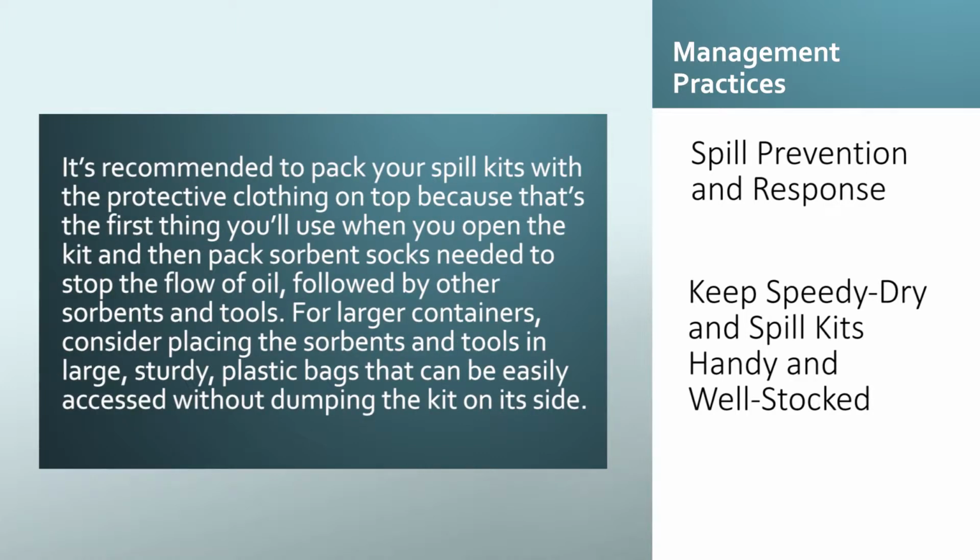It's recommended to pack your spill kits with the protective clothing on top, because that's the first thing you'll use when you open the kit, and then pack sorbent socks needed to stop the flow of oil, followed by other sorbents and tools. For larger containers, consider placing the sorbents and tools in large, sturdy plastic bags that can be easily accessed without dumping the kit on its side.